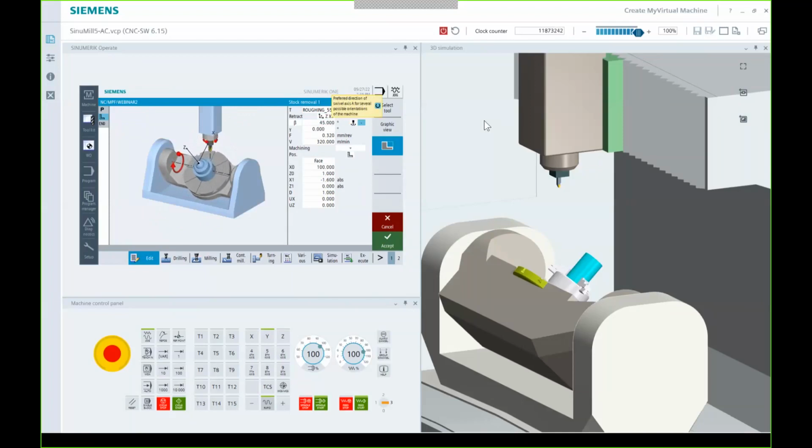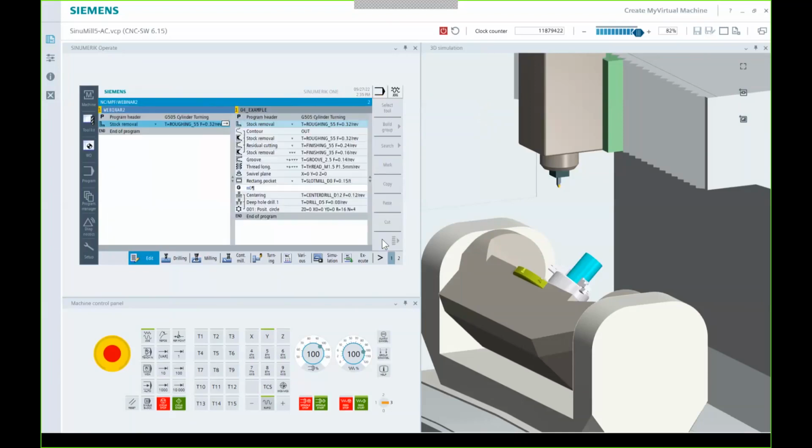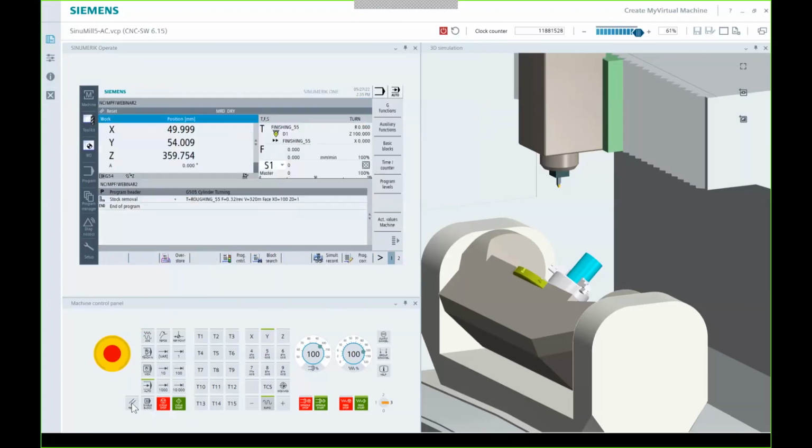This is also a new field where, if I wanted to mill or turn this with the tool pointing forwards or with the part pointing forwards or backwards, I can change that by changing this field here. Right now, it's in a negative. So watch what happens when I go to machine. I'm just going to go ahead and put this into execution right at the start, machining this part.